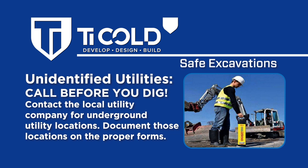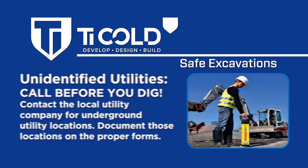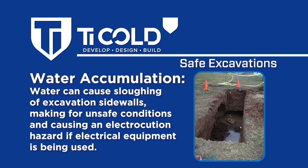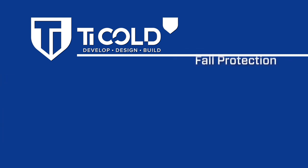Unidentified utilities. Call before you dig. Contact the local utility company for underground utility locations. Document those locations on the proper forms. Water accumulation. Water can cause sloughing of excavation sidewalls, making for unsafe conditions and causing an electrocution hazard if electrical equipment is being used.